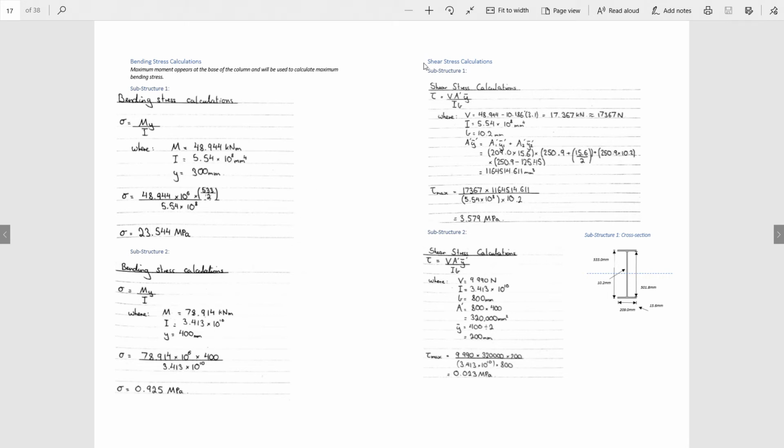So our shear stress calculations. The big key variable in these two situations is basically finding out our centroids from that neutral axis here. Worked out our Y here, worked out our A here. This being a column, this being an I-beam, they're going to have vastly different calculations.